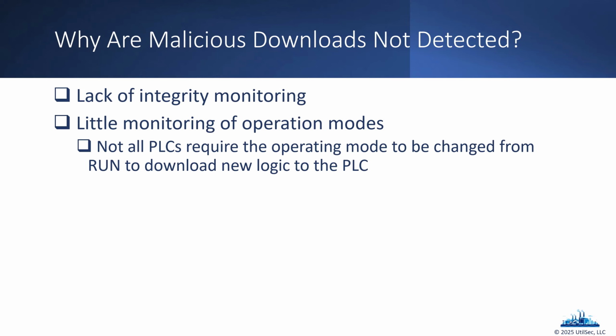But if we have attackers, or what if it's just a PLC technician in the environment making changes that aren't authorized, how are we not catching this? Operators are not checking the integrity of the files running in memory. Think of a file where we can have a file hash or a checksum to tell us, is this good or is this bad? We're not doing checksums, we're not doing integrity monitoring, at least most environments are not.